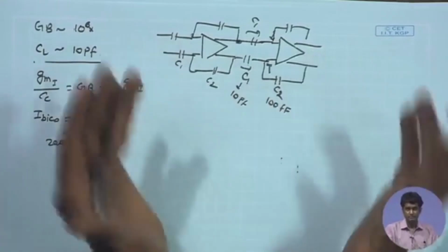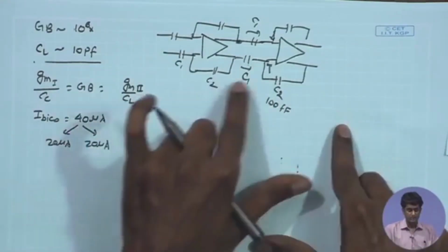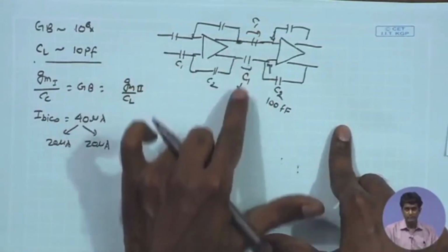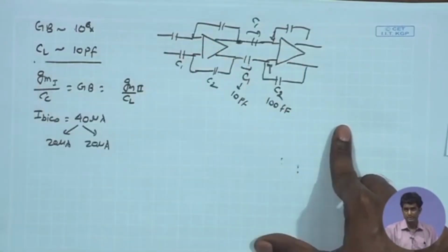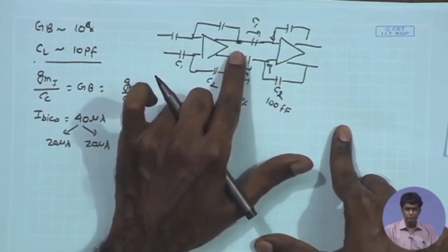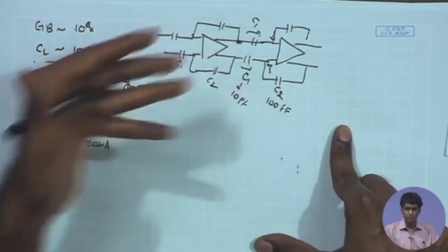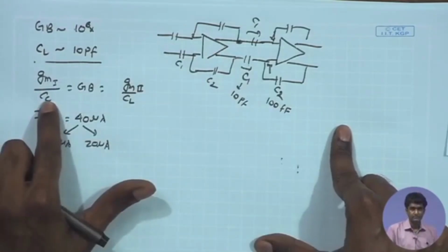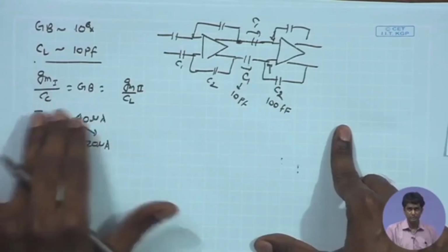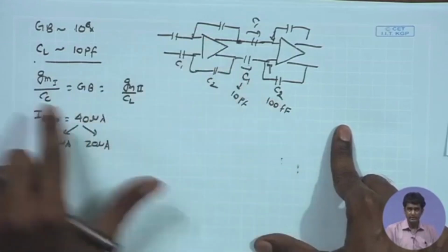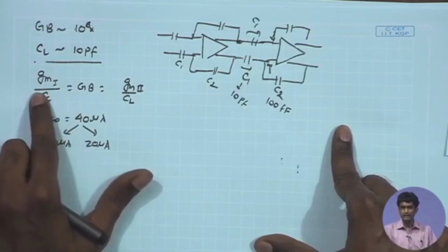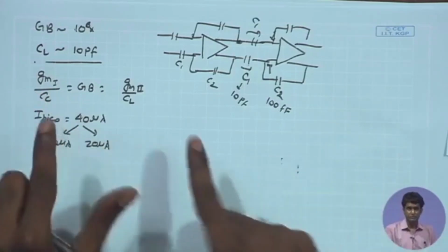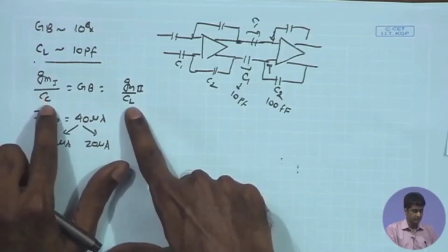If you look at the physical design of the chip, the area of C1 will be much larger than the area of all the other transistors building this amplifier, and therefore it would be prudent to minimize the values of C1 and also the corresponding compensation capacitor. If the compensation capacitor is close to C1 or CL, then this also becomes a dominant factor and consumes a lot of area. So, it would be important to minimize both these values, CL and CC.